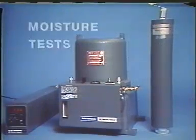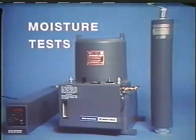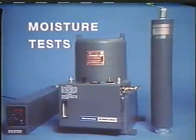A moisture analyzer is often used to check for water in the feed and in the recycled gas stream. A precise amount of water must be kept in the system to spread the chlorides across the catalyst and keep it active.